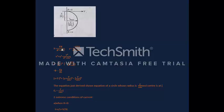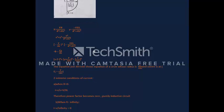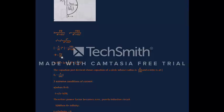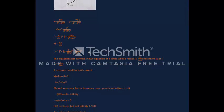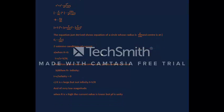So x = VR/(R² + X²), y = −VX_L/(R² + X_L²). As you saw, the equation comes out to be x² + y² = V²/(R² + X_L²). Therefore, −(V/X_L) × VX_L/(R² + X_L²) turns out to be −Vy/X_L. So the equation comes out to be (x − 0)² + (y + V/2X_L)² = (V/2X_L)². The equation just derived shows a circle whose radius is V/2X_L and whose center is at (0, −V/2X_L).